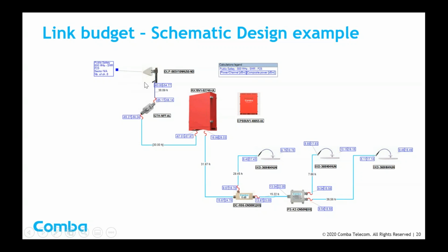On the uplink side, the design even has to incorporate the signal loss from the donor antenna to the tower. That's called free air loss. Even though it's going through air, the signal loses something. So this has to be very precisely calculated to deliver a signal through the tower that is going to make the call quality good, yet will not desensitize the macro, and will not put too much noise on the network.